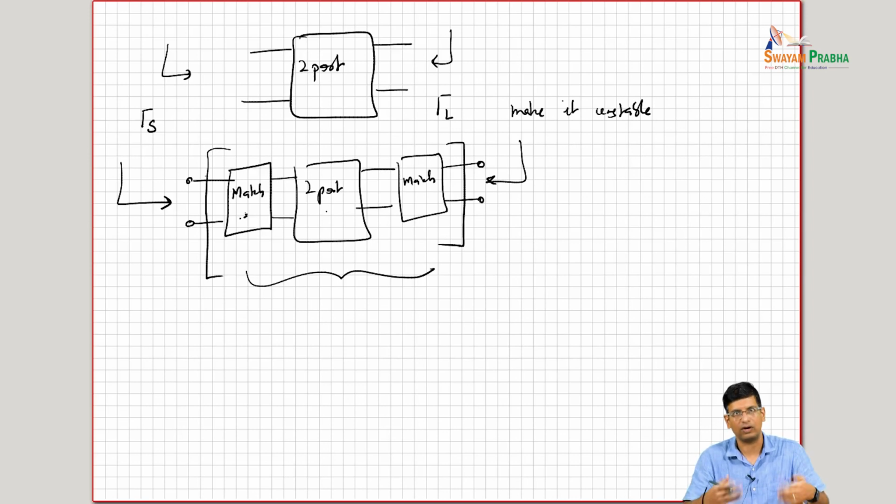But you are trying to design for a situation where it isn't that way. For example, if you're designing a power amplifier connected to an antenna, then when a hand comes close to the antenna, the impedance changes. And so the matching network is no longer providing optimum, it's providing some other network. So that's the design problem.